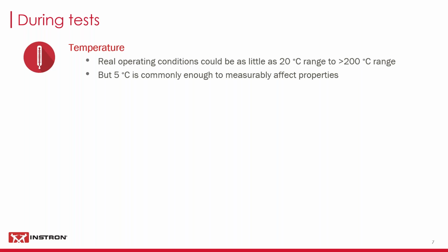So, moving on to perhaps the interesting bit from Instron's viewpoint, when you come to do the test, three things to look out for. Temperature. Whatever you're going to use your composite for in the end, it's going to have a temperature range that it's going to operate in. Even if you say it's only ever going to be room temperature, there's probably going to be between 15 degrees C up to 30 degrees C. So you're going to see a 15 to 20 degree operating temperature range.